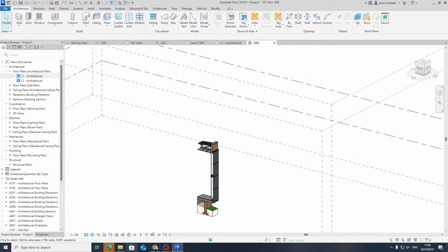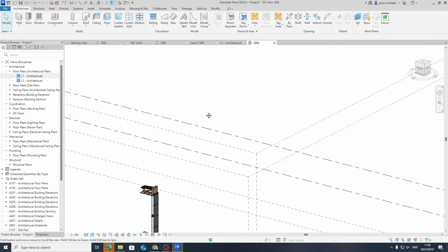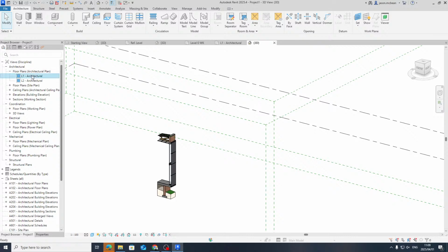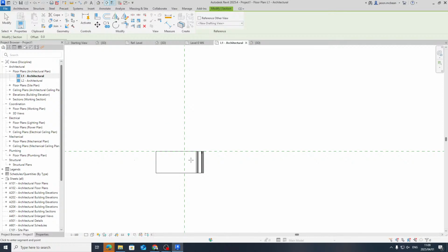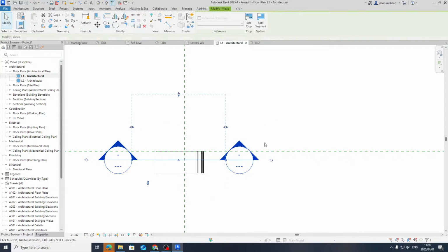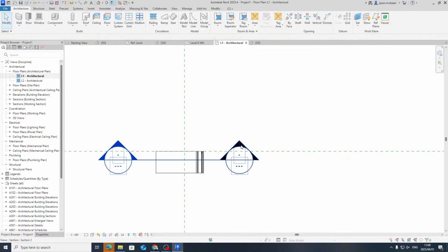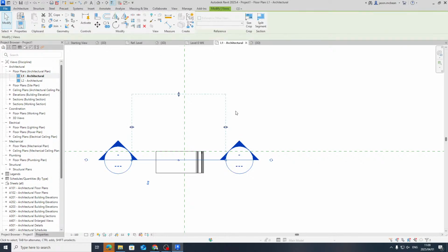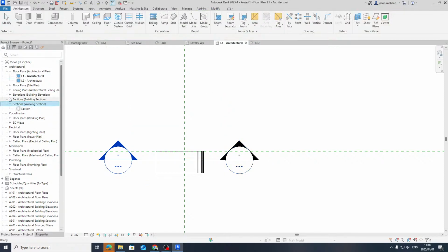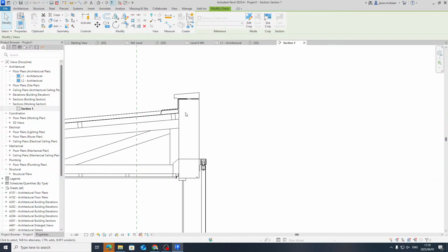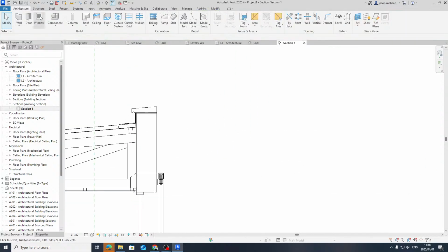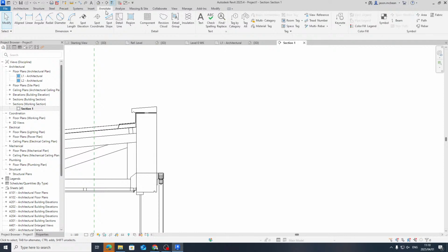Now, why do we want to use Revit? If you want to document these, I'll just draw a quick section through this object. So if you want to start doing documentation, now this won't work as well, unfortunately, because it's not using my template. You'll see that these things are very polluted if you don't use the right template. But what it allows me to do now is I can start documenting, so annotate.